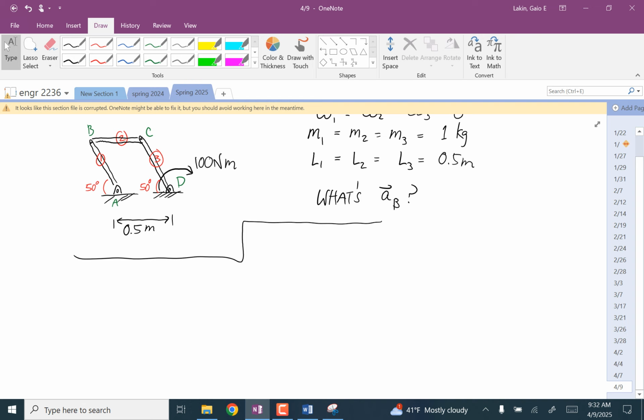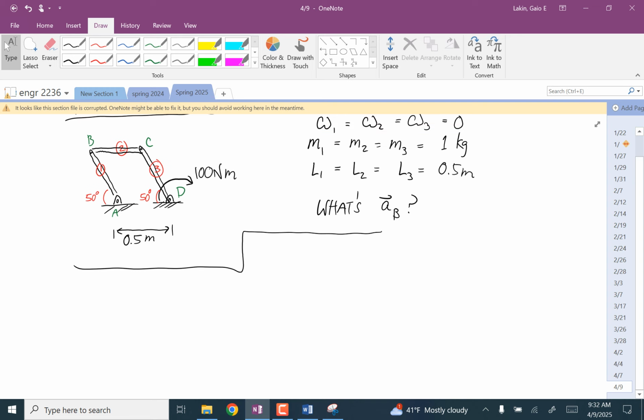Okay, let's think about variables and make sure it makes sense. This can be a little tricky to think about, but I'll try to walk you through it. So we're expecting to have 9 variables show up in the equations. On this first one, if you think about a free body diagram, we'd have a reaction force RA, full vector, and then a reaction force F12 up here.